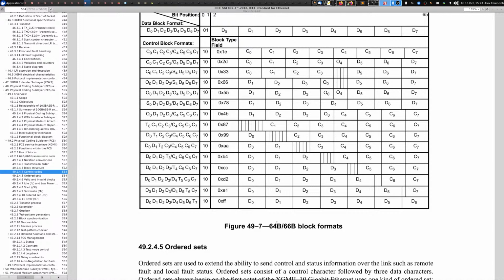And gigabit Ethernet over fiber uses 8B/10B encoding, and in that case, the link actually runs at 1.25 gigabits per second. It's also the same thing for SGMII, which is a serial version of GMII that uses a single pair of wires. It's actually almost the same format as gigabit Ethernet over fiber.